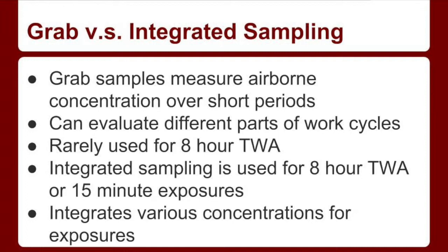Grab samples alone are rarely used to estimate an employee's 8-hour time-weighted average exposure. This is because they do not account for the time between samples. However, they can be used as a screening method to determine whether more extensive sampling is needed.